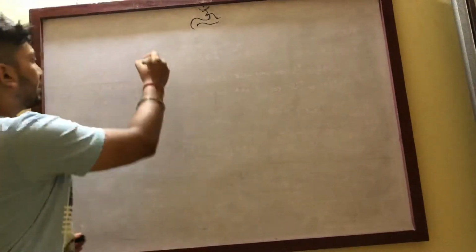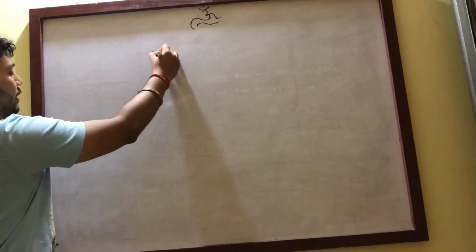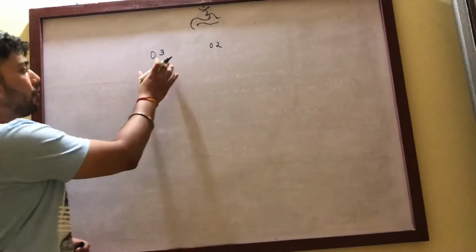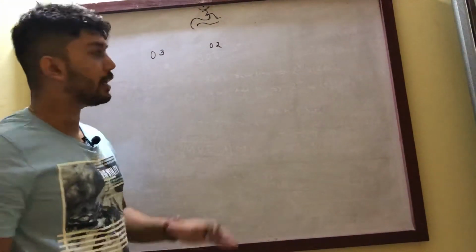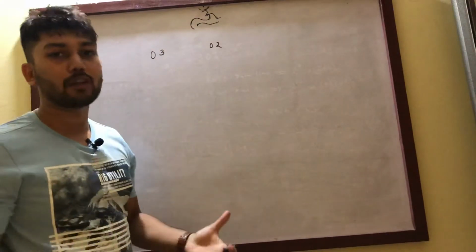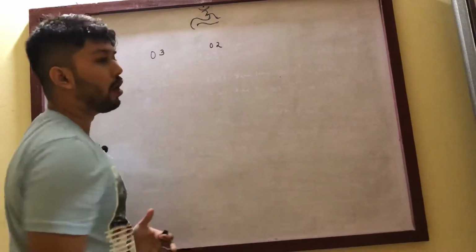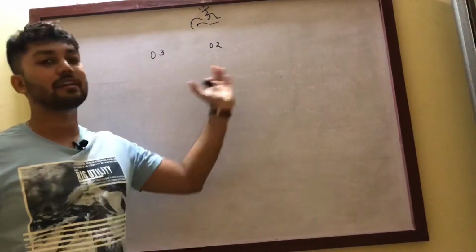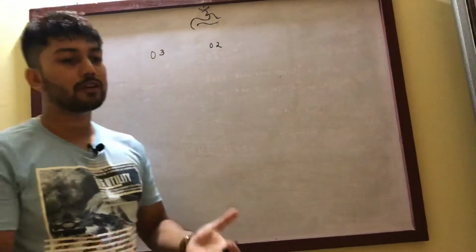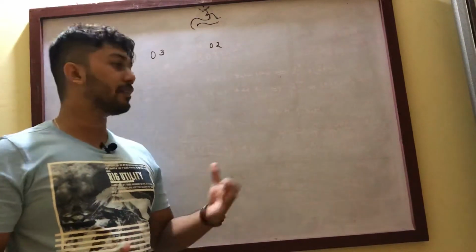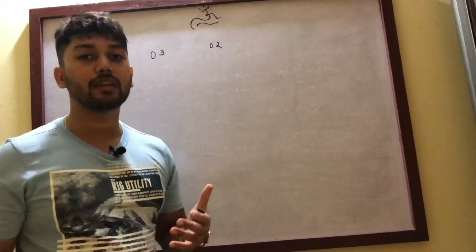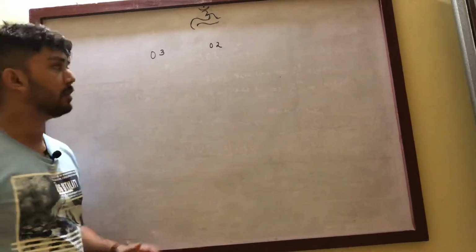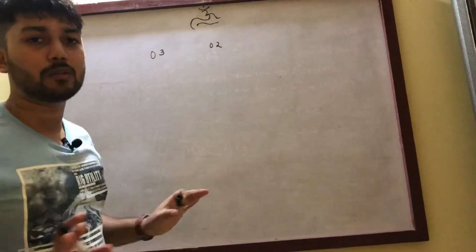So let us start with, say, you have 2 data, 3 and 2, that you need to add. But first I'll make sure which data type you are using, whether you are writing in decimal or in hexa. In the 8085 microprocessor, by default data is written in hexadecimal. So if you are trying to add data given in decimal, you first need to convert it into hexadecimal in order to put it into the 8085 microprocessor. Here 3 and 2 are both in hexadecimal, so I am not worried.